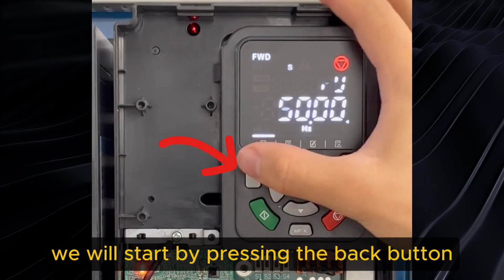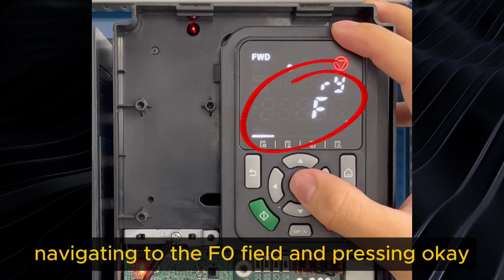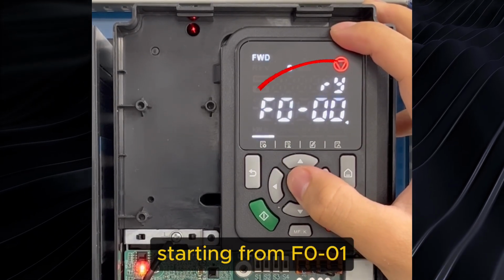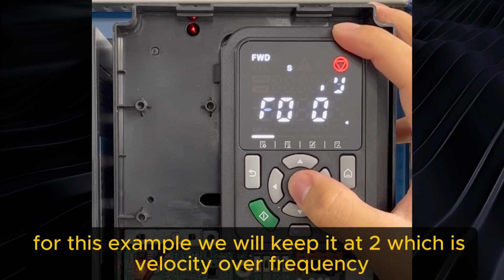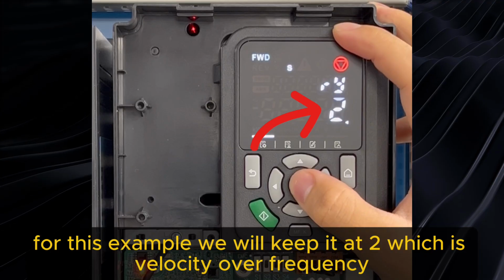We will start by pressing the back button, navigating to the F0 field, and pressing OK. Starting from F0-01, we can change the motor control mode. For this example, we will keep it at 2, which is velocity over frequency.